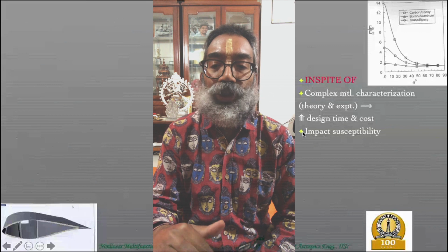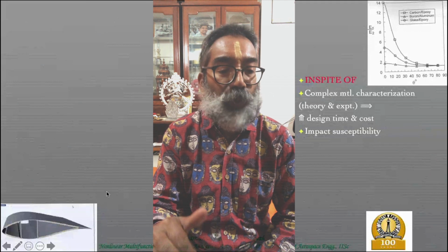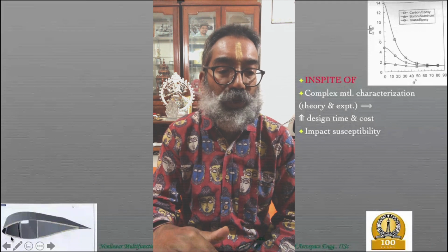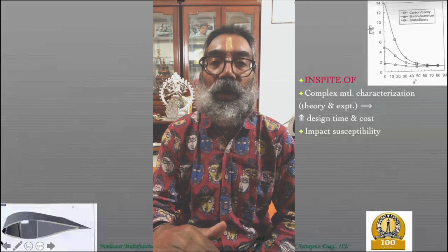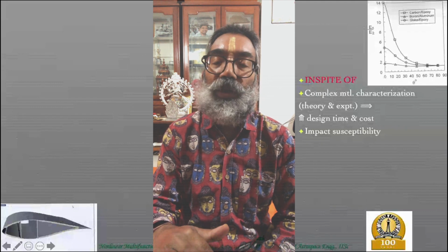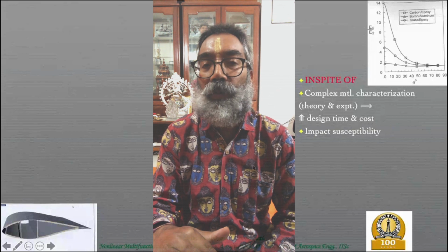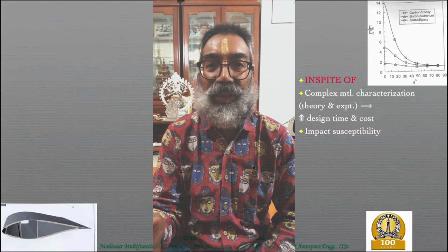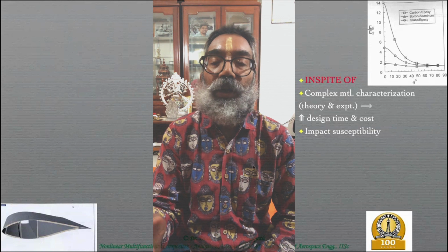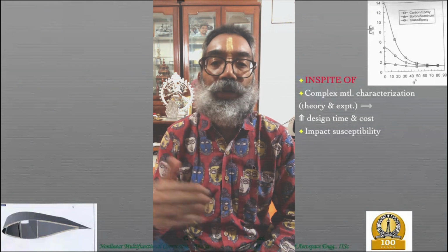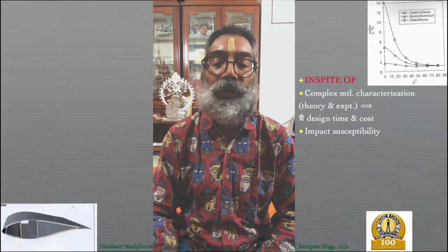So this is an issue that we'll have to deal with, and one way, of course, as we saw, is to introduce that kind of covering with a metal. The other is to have an NDT/NDE procedure, that is a non-destructive testing and evaluation procedure, at a regular interval, so that you take care of this issue as well.